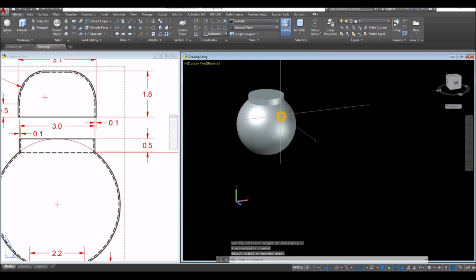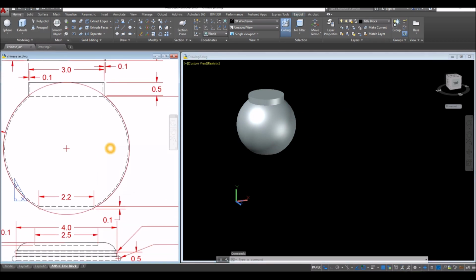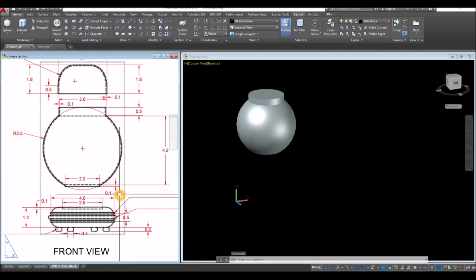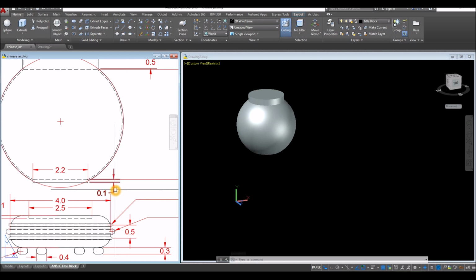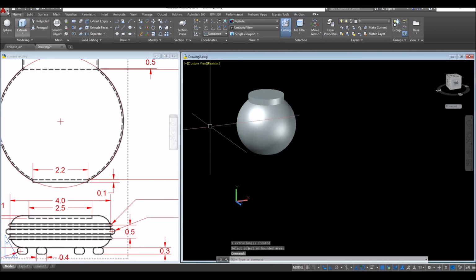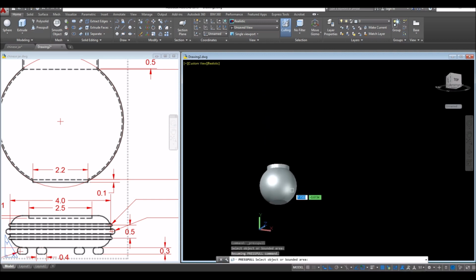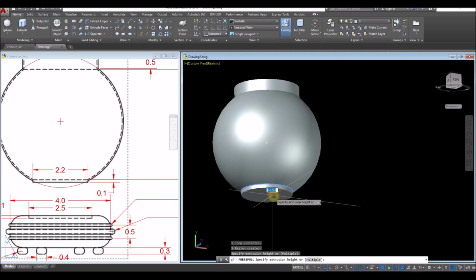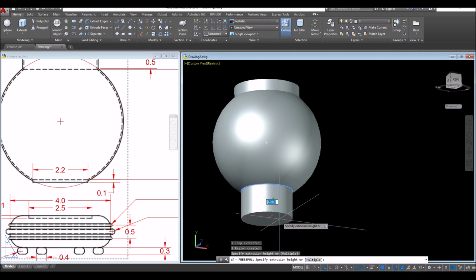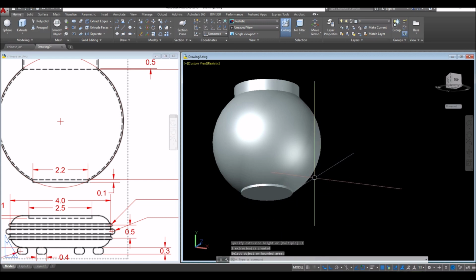And at the bottom, the extrusion is 0.1, this one here. So repeat the press pull command, hover over on this face, left click. Once it turns blue, just release your finger, bring it down for 0.1 and enter.